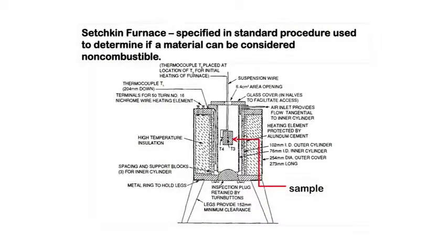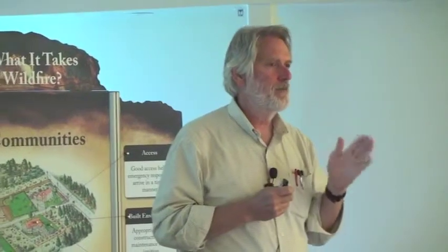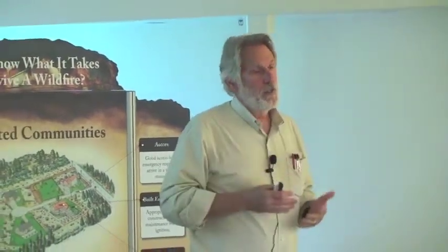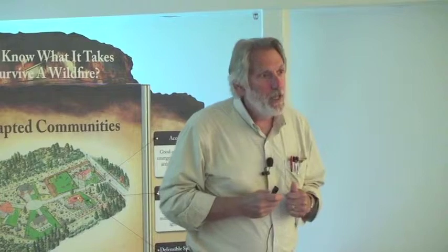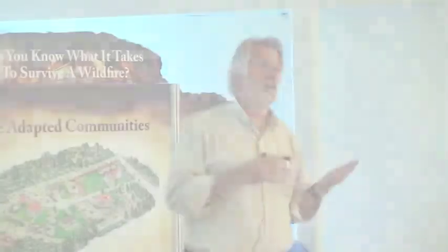This is a particular kind of furnace that is used to determine whether or not a material can be considered non-combustible or not. So there are certain things that you sort of know, you feel in your head it's non-combustible, like lightweight concrete. You might think, well, that's non-combustible. Stucco, you might think, well, that's non-combustible. But fiber cement, people think it's non-combustible, but the fiber in fiber cement is a wood fiber. So really, it's sort of a function of how much is in there, maybe. And so they, for example, would use this test to confirm whether they're non-combustible or not.